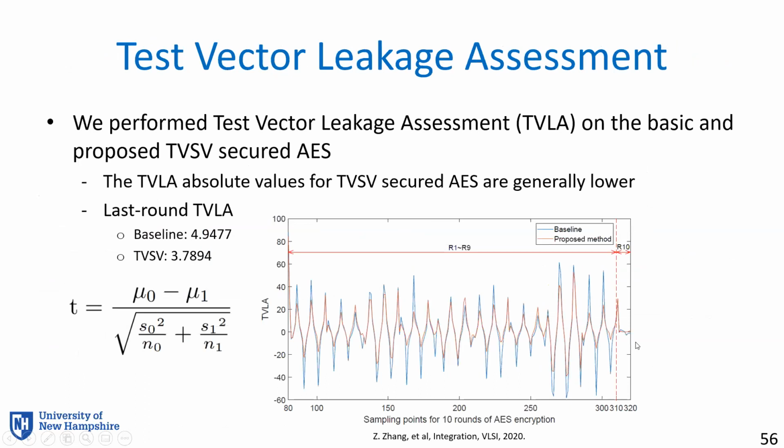We understand that if we apply a countermeasure to address one attack, we have to consider that the countermeasure itself may leak information. That's why we performed a test vector leakage assessment, TVLA, to see whether our countermeasure will leak some new information.